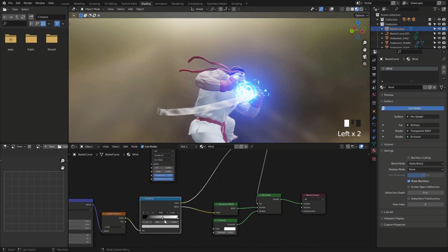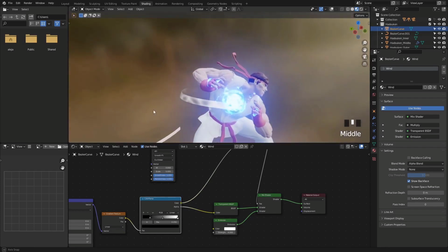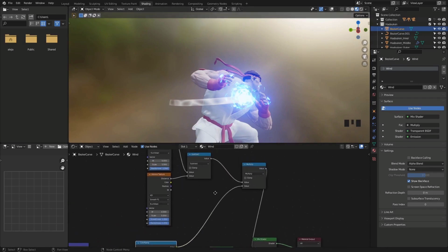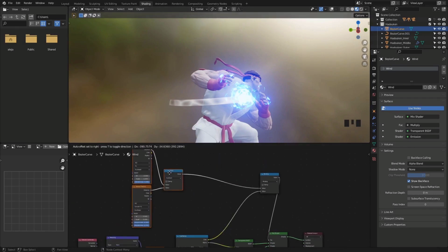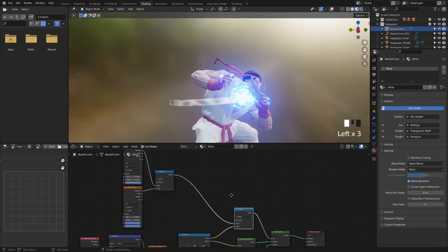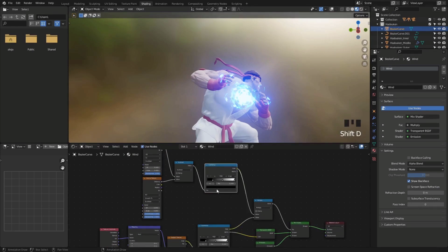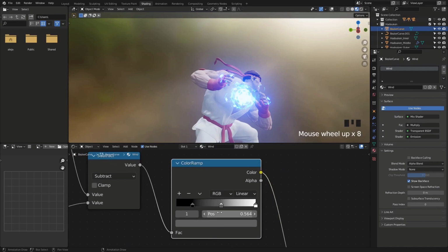But I want to push it a little bit further and add a gradient or a color in the middle. What this is going to do is, the lower I bring it, the more gradient is going to show up for the end. And I want something kind of like that. So there we go. Now we're making full use of the shader here, of multiplying it and then connecting the two together like so. But I also want to use a color ramp here to tighten the look, but we don't need this middle gradient right here anymore. So we'll just focus on these.